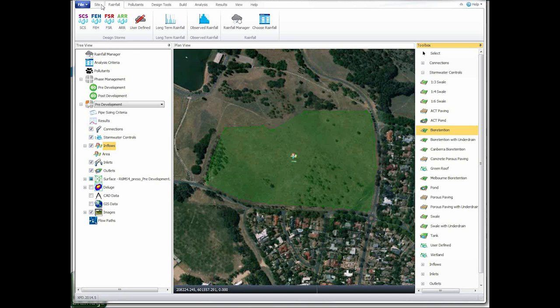We start with our site information, details, drainage areas, the actual ground surface, things like that. We have to have some rain, typically. That's kind of our reason here, looking at water on the ground, and we'll have a number of ways to look at and put in rainfall. And then pollutants, which is pretty straightforward: all the pollutant data that we want to include for an analysis.